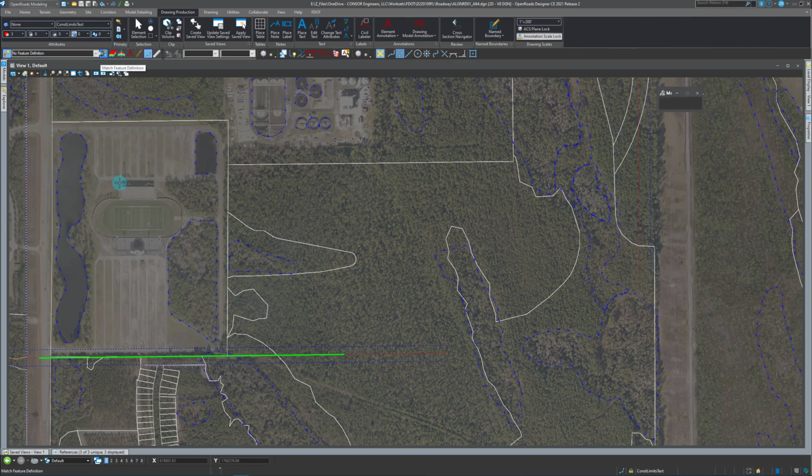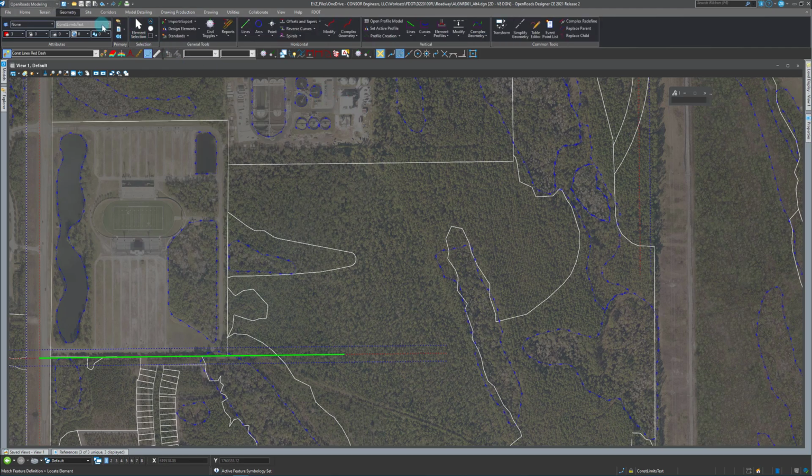So I'm trying to keep doing the construction line method here where I want to do an arc from element, simple arc from element, from the construction line, and I want to snap to the end of this line because that's setting the tangent distance that I need. And then I can put in my 1375 radius, and I'm just going to pull this out pretty far. So it just extends way beyond where it needs to go, just like I do with the tangent construction lines.